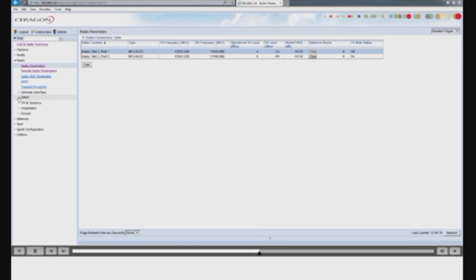These scripts define how the radios behave according to the communication standard, in what channel bandwidth and at what capacity they can perform. First, go to the MRMC status submenu to observe the current operational modulation and capacity, which for us should be 0, as the parameters are not configured.